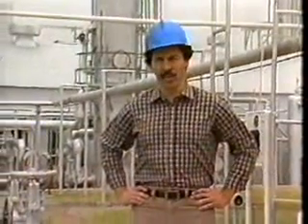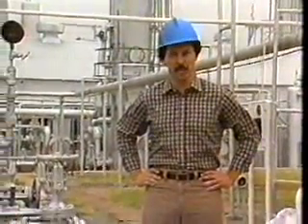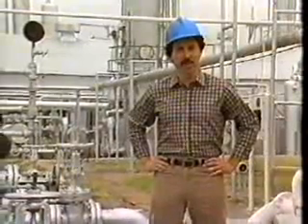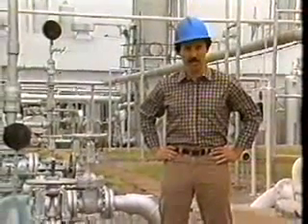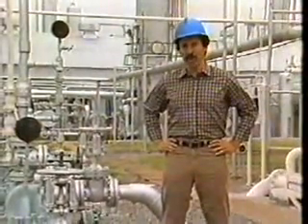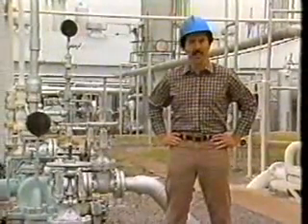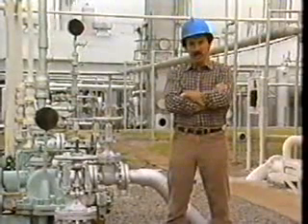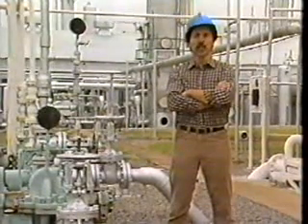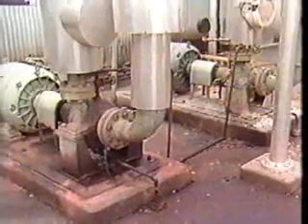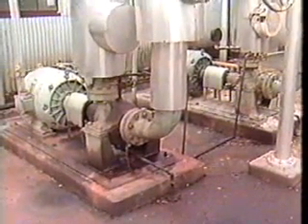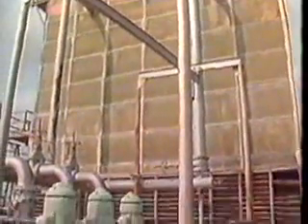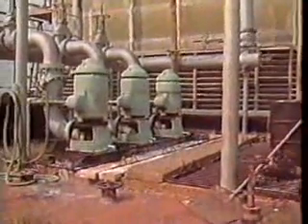Those with pistons or gears are called positive displacement pumps. And those we'll talk about today, centrifugal pumps. Another module focuses on positive displacement pumps, so we won't spend any time on those right now. So, when are centrifugal pumps used? Usually when you have to move a lot of fluid, like emptying storage tanks, moving processed fluids in gas plants, providing emergency fire water, circulating cooling tower water, and, well, many other applications.